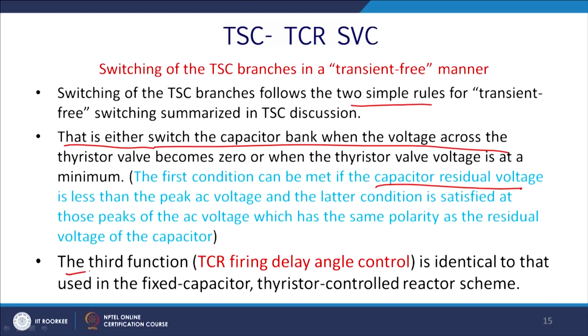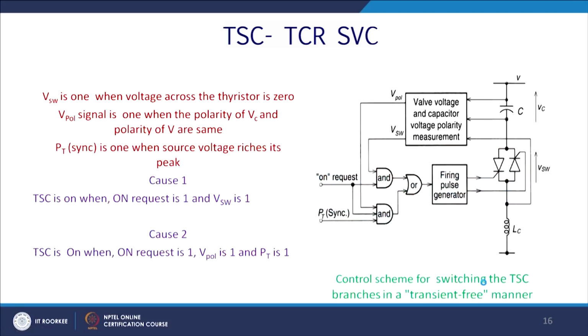For the third function, the TCR firing delay angle is identical to that used for the fixed capacitor and thyristor controlled reactor scheme; there is no change. So, this is the control logic. You have to sense the voltages. First of all, it will sense the pole voltage, and we also have to sense the voltage across the switch. We want to have minimum stress across the switch.